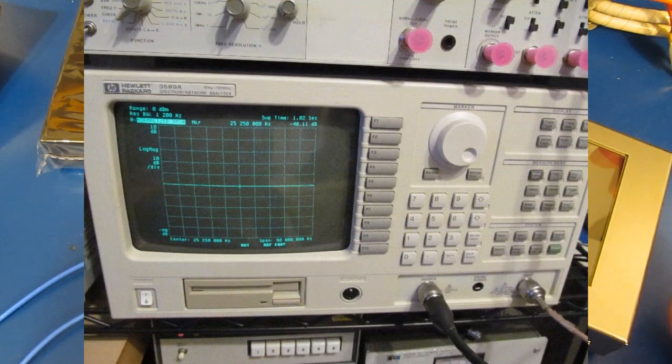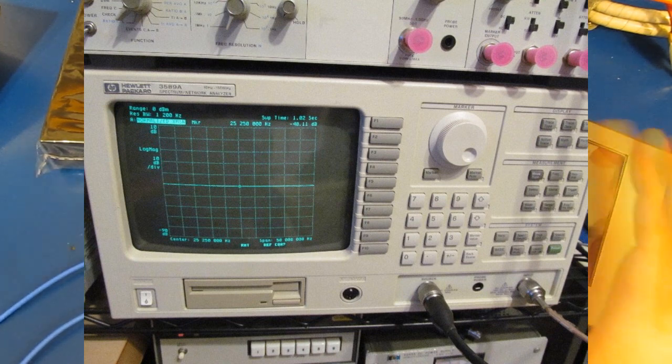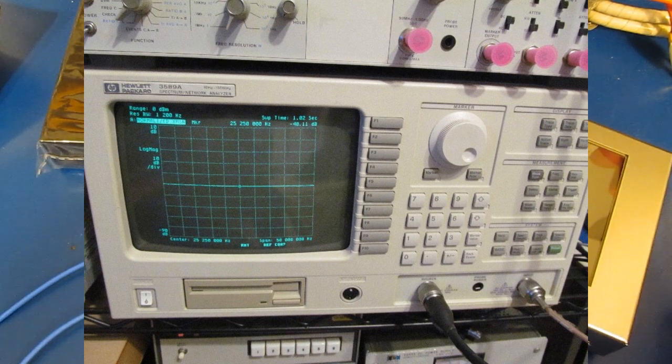I also own an HP 3589A. That's a little newer network analyzer. It's kind of an oddball in that it's actually a network analyzer as well as a spectrum analyzer. It can do vector network measurement, but in order to do that, you have to attach an external directional coupler. That particular VNA is good all the way down to 10 Hertz. That would be ideal to measure these PDNs. Unfortunately, the upper limit of it is 150 megahertz. So again, not a real good solution.